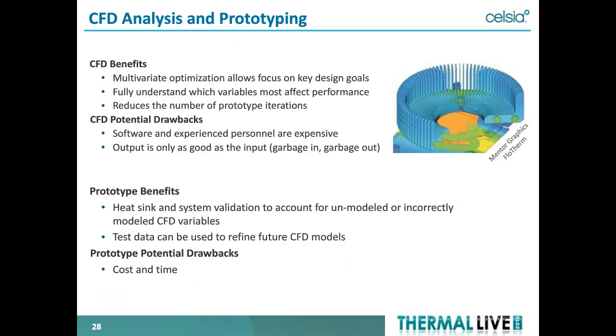Obviously, the next step is to go through a CFD analysis. I don't think we have to talk about the benefits and drawbacks of that. I think there's a presentation from Mentor that's going to go through some of that stuff. One of the potential drawbacks is you have to have enough validation of your model before you can rely on it. So always validate your model. Either you have enough information from the previous design, or before you believe this, you want to build and get some real data.